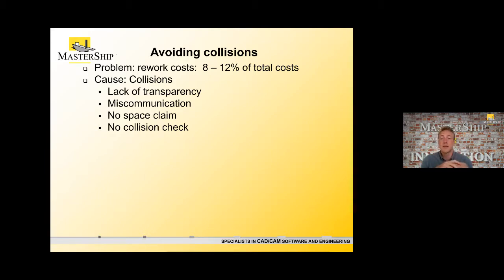And the second type of collision is when 2 construction elements collide with each other. For example, when a continuous stringer is going through a bulkhead. That typically happens when you have a miscommunication. For example, two draftsmen working in the same section on adjacent drawings, but they are not aware.